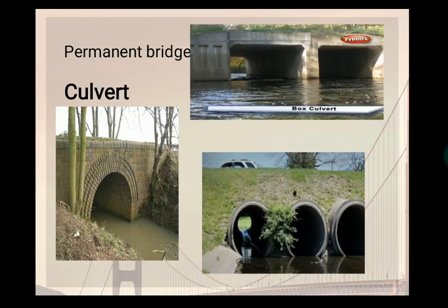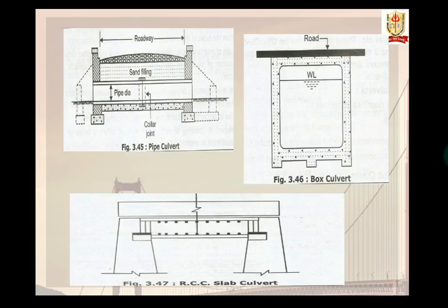The pipe is surrounded at both ends with masonry work in the form of arches and or by stone pitching. When the height of the embankment over the pipes is about 6 meters, it should be given a proper all-round cushion. It should also be provided with suitable concrete bedding at the bottom.